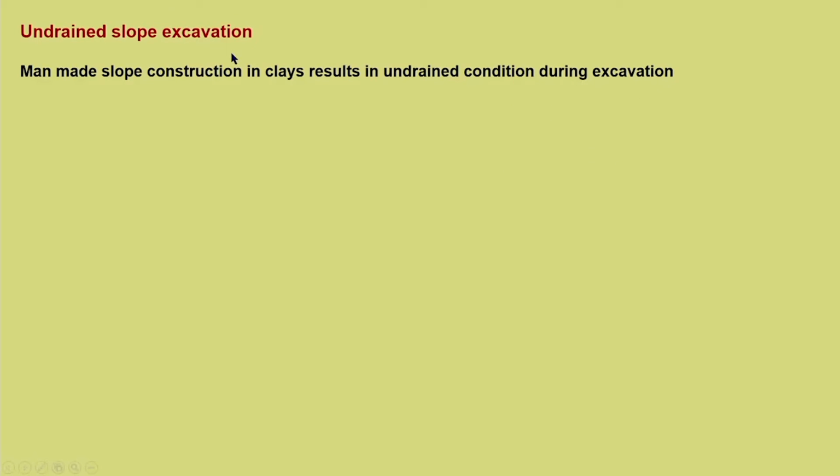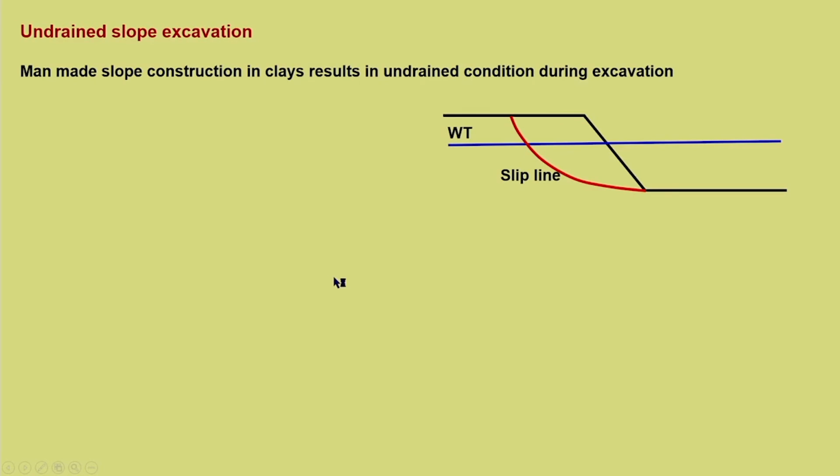So here also we are dealing with slope, but a finite slope instead of an infinite slope. Now this is a given finite slope. This has been created because it got excavated from this end. So consider initial isotropic condition with initial U0.